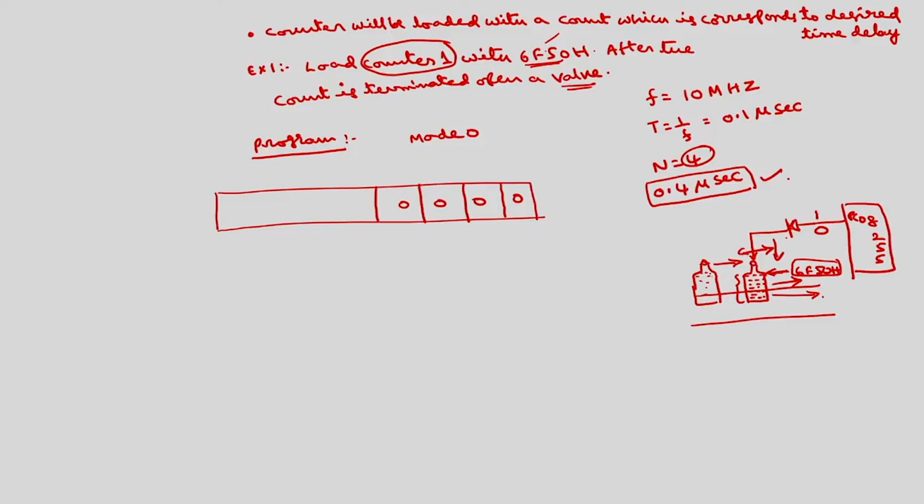These 2 will decide RL1, RL0. So this is 1 1, which is total 16 bit count. First it will take the lower order 8 bits, then higher order 8 bits. Because our count is 16 bit, you have to load with 1 1, so that it will first take the lower order 8 bits and then the higher order 8 bits of the count.